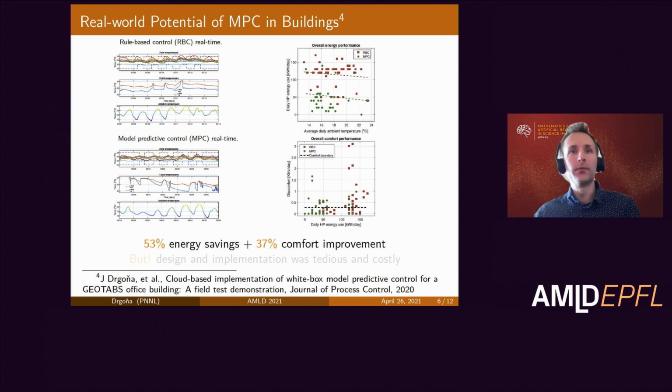The bottom figure is the trajectory of the ambient temperature, which acts against us. In the middle, we have the supply and return temperatures, which represent our control decisions. You can see that under the rule-based controller, these control decisions are pretty static. They don't vary much with variations in the ambient temperature or with the state of the dynamics of the building.